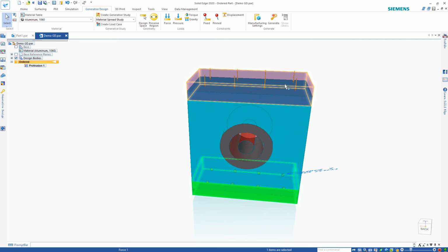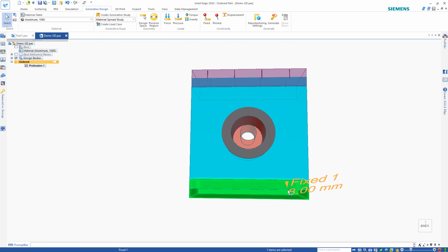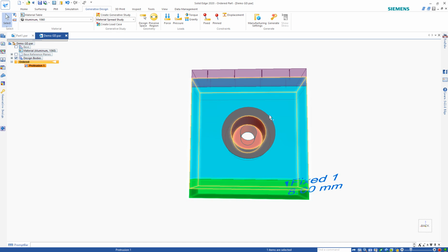All right. This is because, let's say, for example, the top surface actually withstands the pressing force. So if you remove material from these areas, there will not be enough space for withstanding the force. Same thing here for the bottom fixture. This is where it connects to the ground or other things to fix the part, so it should not be changed. Okay.